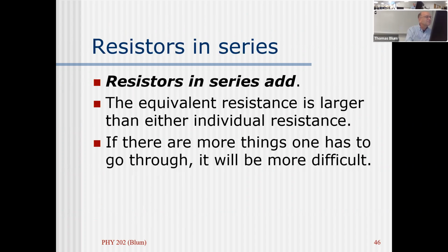Anyway, okay. So resistors in series add. The equivalent resistance is larger. They have the same current, and the voltages between them add up to the overall voltage, and the voltage across the bigger resistor is bigger because it takes more energy to do the bigger task.